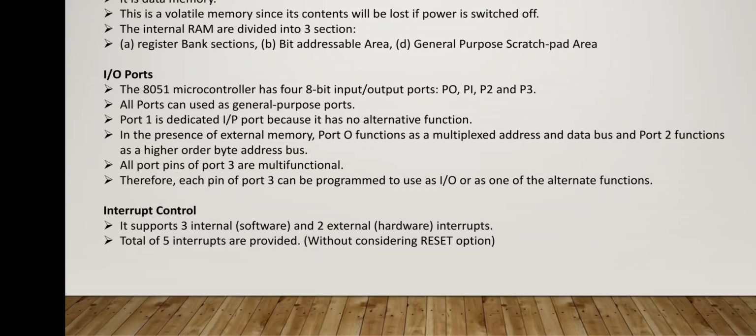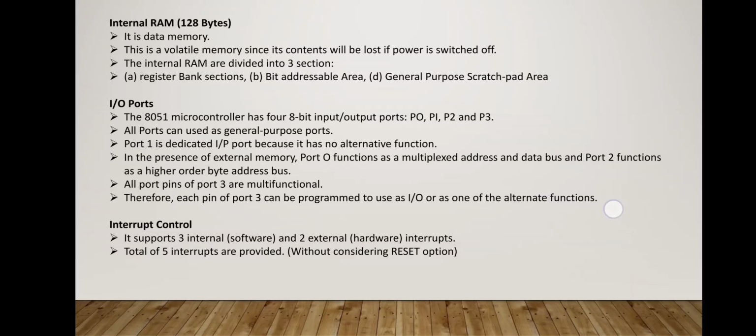Then we have interrupt control. It supports 3 internal, that is software interrupts, and 2 external, that is hardware interrupts. External interrupts are taken from the INT0 and INT1 pins, and it has a total of 5 interrupts without considering the reset option.